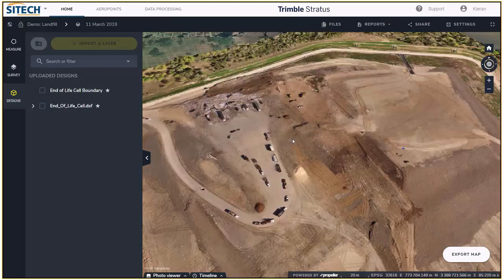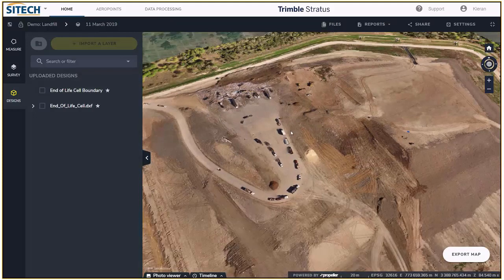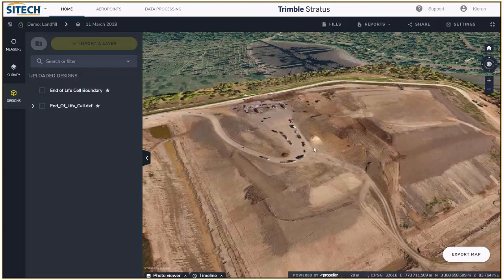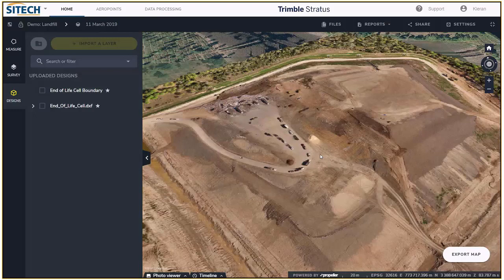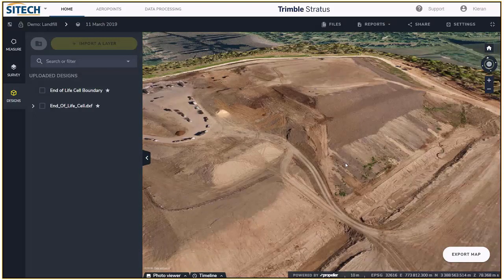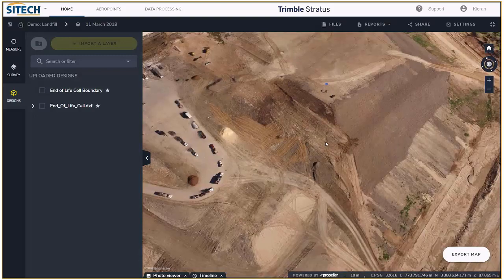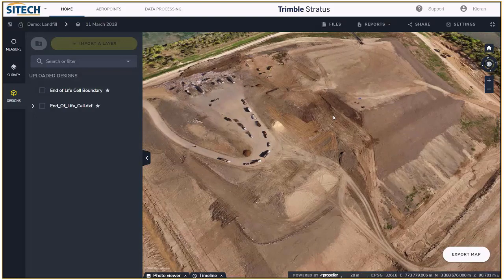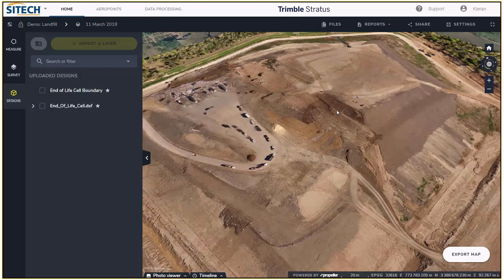Incorporation of terrestrial laser scanning data. So you may have seen at the start I showed we can upload data in point cloud form. UAV data, great, got a lot of applications, but there's certain things it can't do in terms of really capturing under the sides of bridges and things like that. Yes, technically there are ways we can do it, but often there's urban environments, parts of the world that don't work very well with drone data to produce a nice looking point cloud.